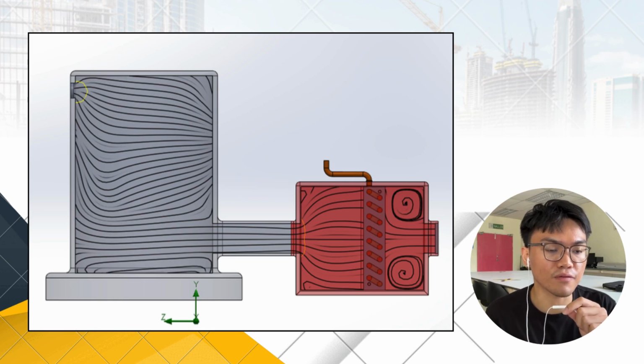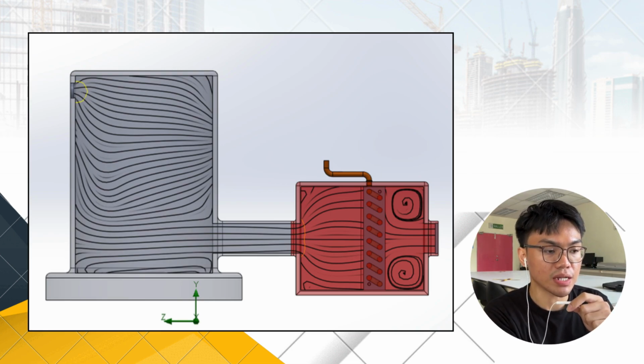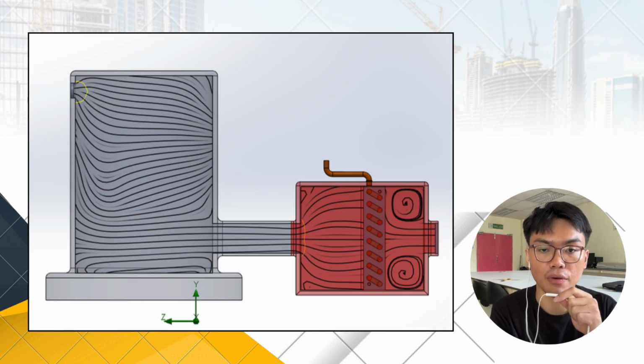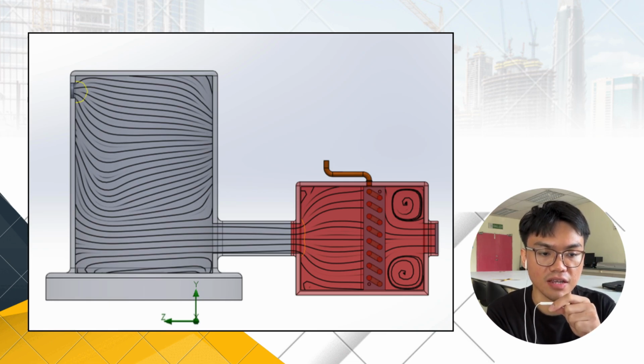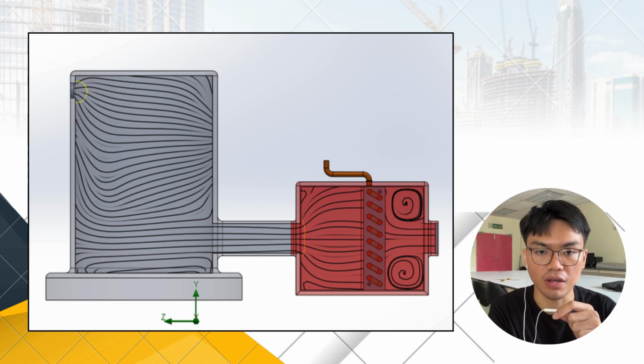This is the airflow cut plot, and we can see the airflow direction inside the heat exchanger housing and the drying chamber. The air enters from the right side, which is where the inlet and the impeller outlet are, and inside the radiator housing, airflow forms recirculation zones, which are useful because they increase the air residence time around the heated fins. After entering the drying chamber, the airflow spreads and circulates across the chamber instead of moving directly in one straight path, which we can see in the airflow trajectories.